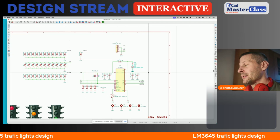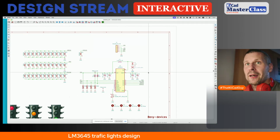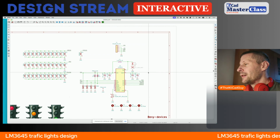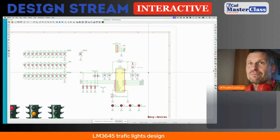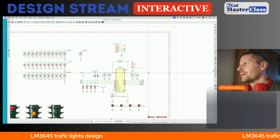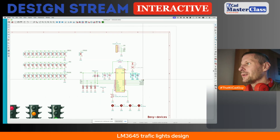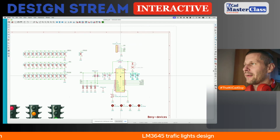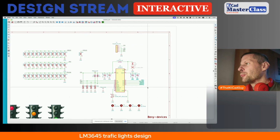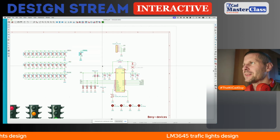I can imagine that the EMC with this driver, when really pushing the limit of the boost converter, can be non-zero, to say it correctly. Anyway, two other decoupling capacitors for the local output of the inner LDO, and for the outputs for the LEDs. These are the traffic light LEDs, and this is the status LED.